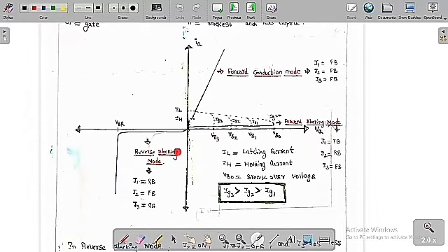If you apply reverse voltage, if you apply negative voltage, then a small amount of leakage current is going to flow, but still it's very small. If you apply more than the reverse breakdown voltage, in this reverse blocking mode, J1 and J3 are reverse biased, but J2 is forward biased. Because of this, in minority carriers, a smaller current flows, nearly 0. This is called the reverse blocking mode. In the reverse blocking mode, J1 and J3 are reverse biased, but J2 is forward biased. So because of this forward bias only, a small amount of current is going to flow.